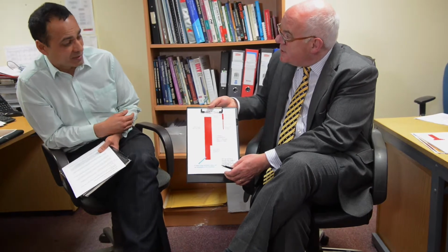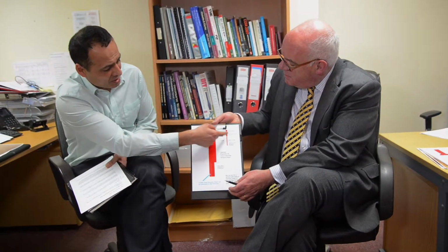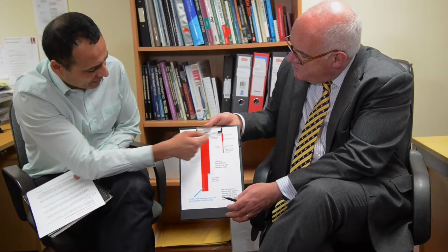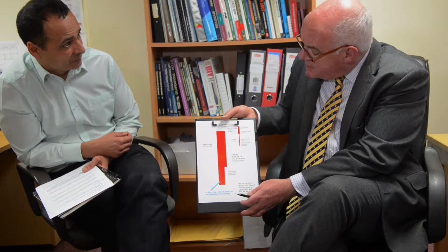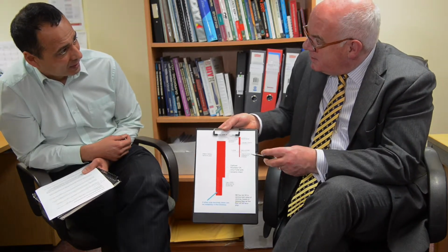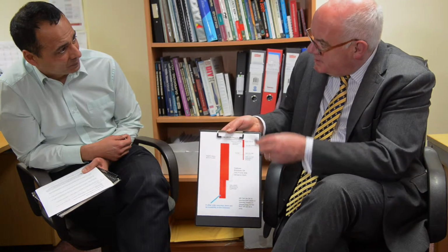Absolutely. So that's where the problems of a destabilised or unstable chimney stack can come into effect. Yes, that's right. You showed in this situation ceiling joists and roof joists. These ceiling joists are actually going into the party structure, but there might be a situation where they don't, so they span from the front of the building to the back. So they might not even be restrained there, even at ceiling level. And if you get a high wind, remember your chimney stack is now extending above the roof by a metre or so. You get bad gales or something, and it's not unknown for chimney breasts actually to collapse onto the building.